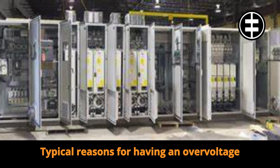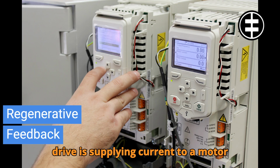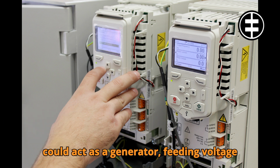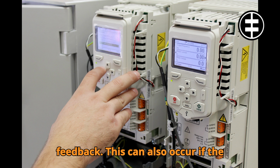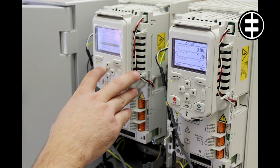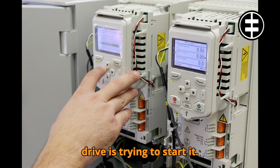Typical reasons for having an overvoltage fault on VFD. 1. Regenerative feedback. If the drive is supplying current to a motor with a lot of inertia, then the motor could act as a generator, feeding voltage back to the drive during periods of deceleration. This is called regenerative feedback. This can also occur if the motor is a permanent magnet-type motor. Another possibility for regen is when the load is already running when the drive is trying to start it.